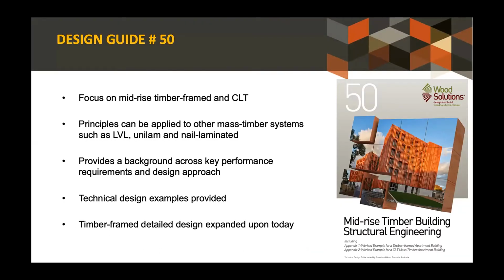what is Design Guide 50? And for those of you that weren't in Adam's webinar last week, this is partly for you guys. So Design Guide 50 focuses on the mid-rise design considerations for both timber frame and CLT as a solution for a mid-rise building. But importantly, those principles, as they relate to CLT, could also be equally applicable to other mass timber systems such as LVL, Unilam and nail laminated, less significant in the market, but still viable options for different types, different projects, different times.